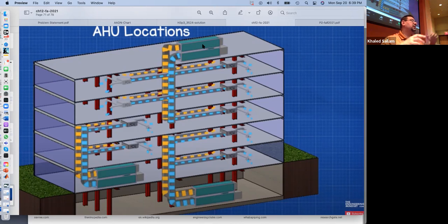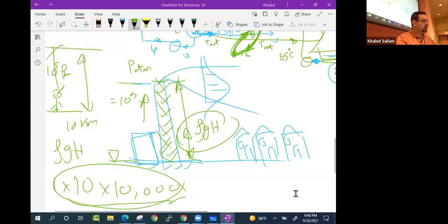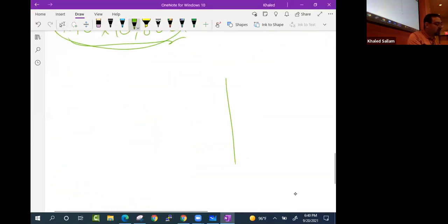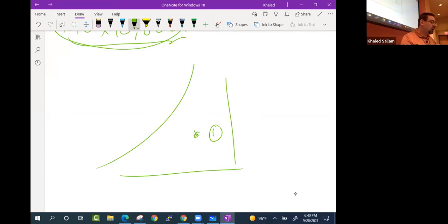So basically what I'm saying is, you guys love to be at 70 degrees. Should I make the duct going into the room at 70, or should I make sure that the exit from this room is at 70? The exit at 70. So the inlet actually needs to be colder, right? Colder and what? And less humid, yes.